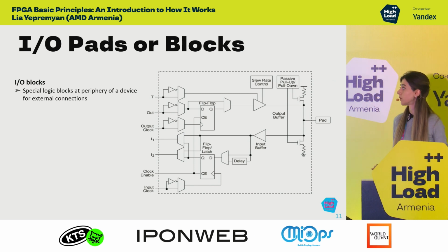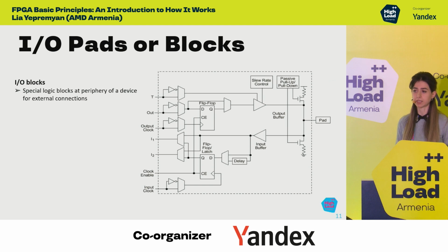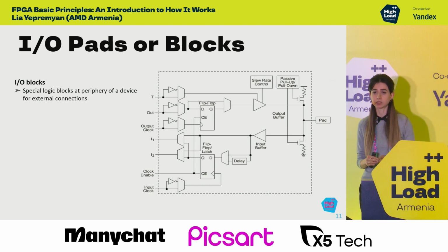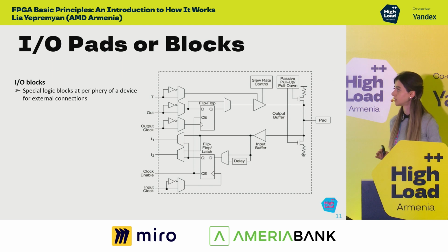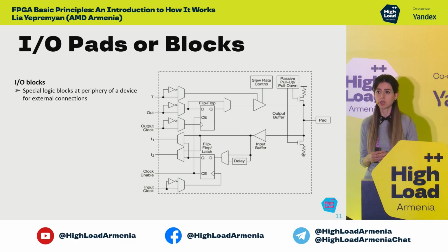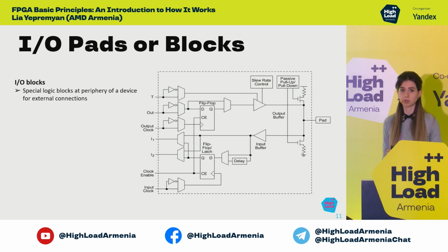Input-output cells are very important in designing an FPGA because there is a large variety of supported voltage and reference standards. And these I/O cells consume a very large portion of the FPGA, approximately 14% of its whole area.